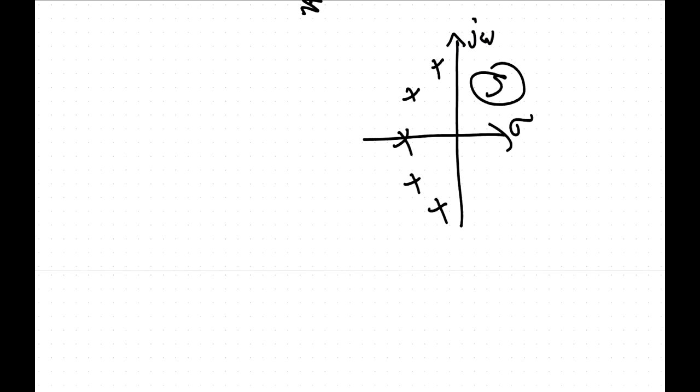And depending on how, if this is a low-pass filter, yeah? If this one here sits on a circle, then it's a Butterworth filter, it's maximally flat. If it sits on an ellipse, it's a Chebyshev filter. If it sits in some other pattern, you can have different types of filters with different properties. But this is not this course. We just assume someone will tell us where to put the poles, and then we can put the poles. Possibly MATLAB.